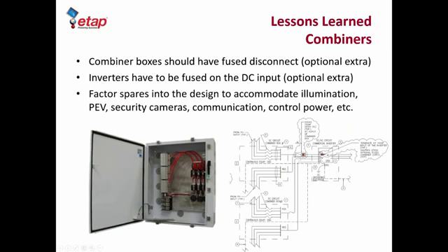So obviously we went ahead and purchased what was standard, and we later on found out during the commissioning phase that we should have had a fused disconnect. So it had to be retrofitted into the system. As you can see here, the fuses were retrofit in, but that essentially caused additional work. So you should pay attention to your local codes to make sure whether a fused disconnect is required or not from the DC side into the combiner. And this fuse is there to protect the cable going to the inverter itself.